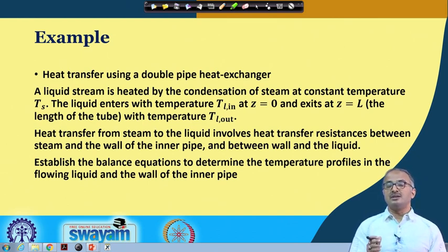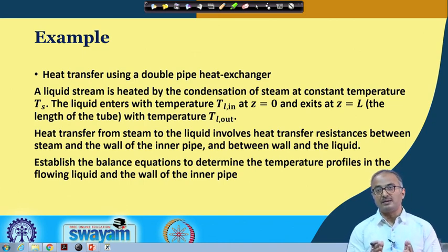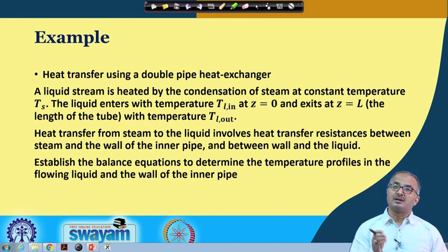On the other hand, you see that if in reality you find that after the condensation, the condensed water may also get subcooled from the saturated state to the subcooled state at the given pressure. In that case also you can say that some amount of heat would be released, and this heat will be coming from the sensible heat transfer from the saturated water to the subcooled water.